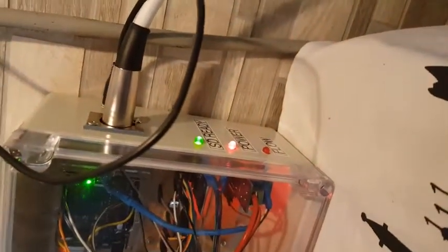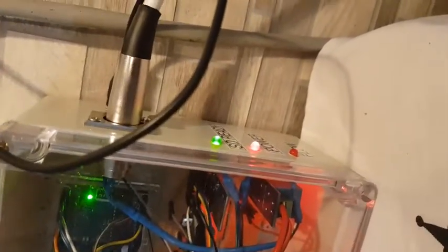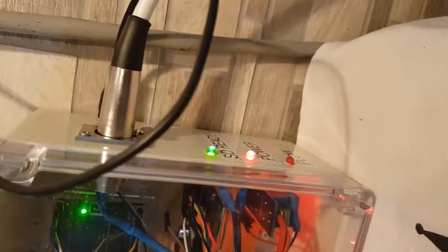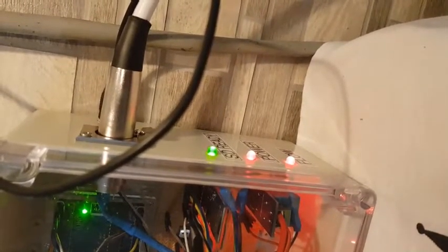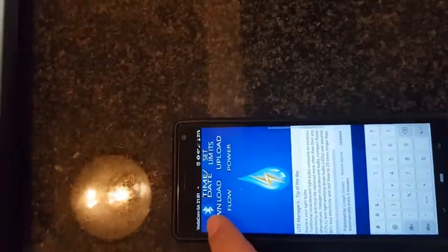As we're currently using more than 300 watts, the light is staying on. If we put on the water and just turn it on, the light won't come on, but as we turn it up to that limit and then turn it down a little bit, it goes off, although the water is still running. So we can set the limits of these LEDs, and we download.